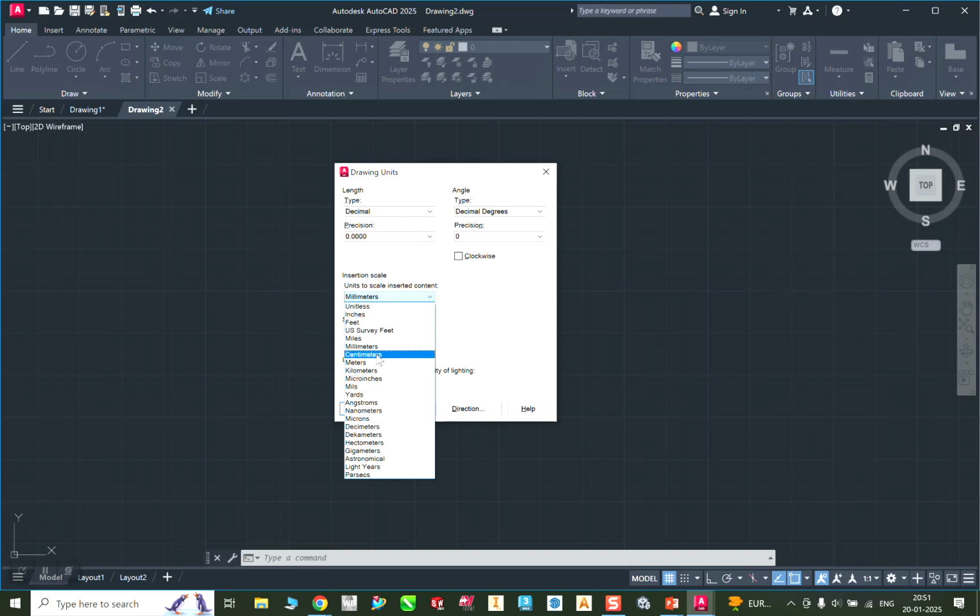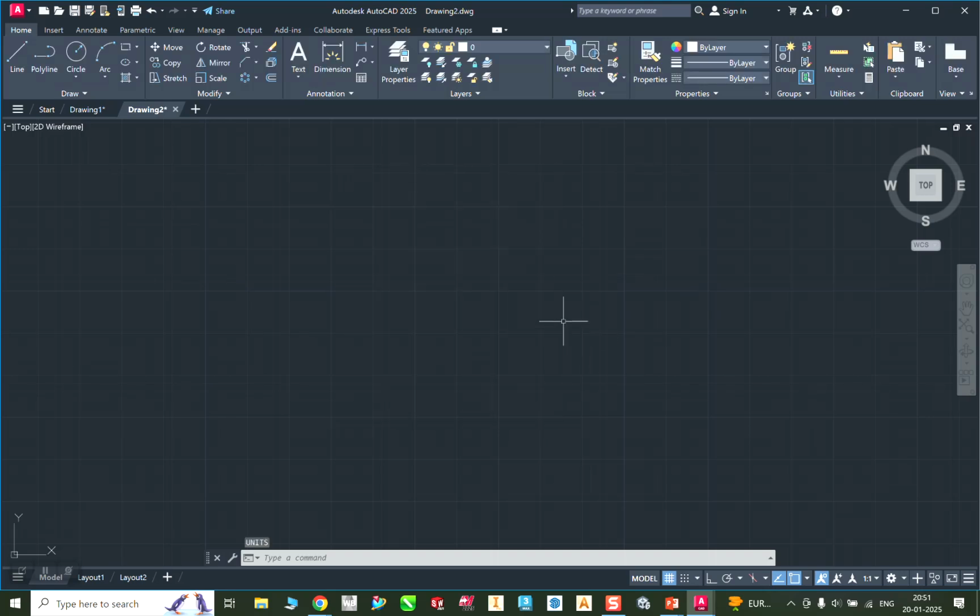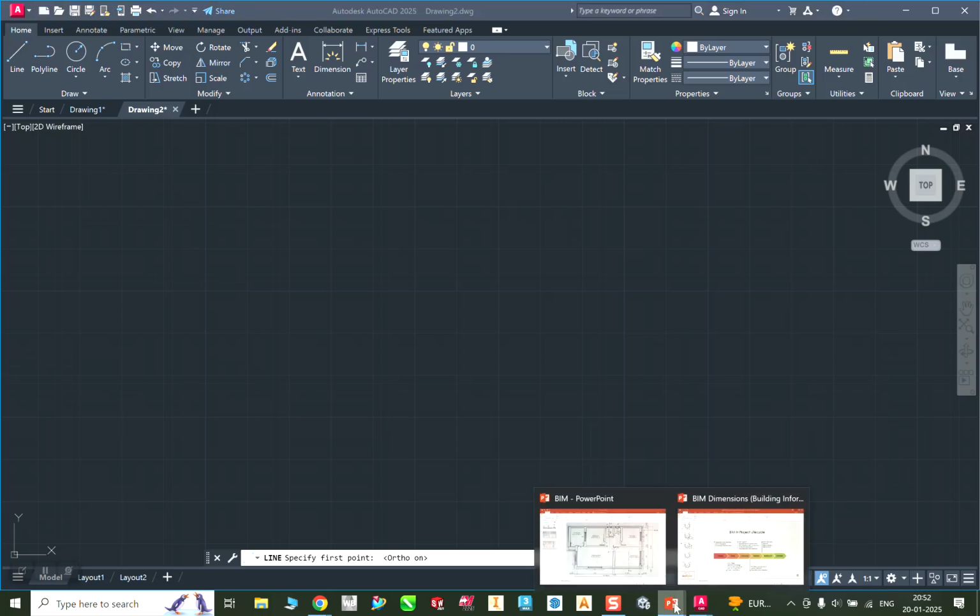Here basically you can see that meters are there, and you can reduce the scale by 0.0 and just do it. Okay, so my geometry is basically in meter now. So when we are going to define our geometry, I'll take that line, click on that perpendicular, and I'll start it from here. We can check out our geometry over here.